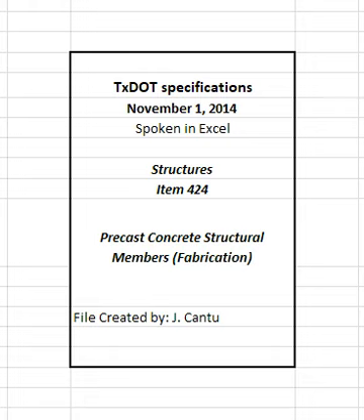Non-stressed members. Precast concrete members that have not been pretensioned or post-tensioned. Prestressed members. Precast concrete members fabricated by the process of pretensioning, post-tensioning, or a combination of both methods. Minor prestressed members. Includes piling, bridge deck panels, and sound wall panels. Major prestressed members. Includes all other prestressed members not listed as minor prestressed members. I-beams. For this specification all I-girders and bulb T-beams are referred to as I-beams.